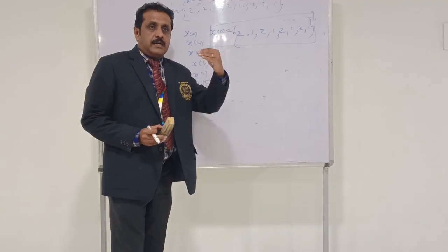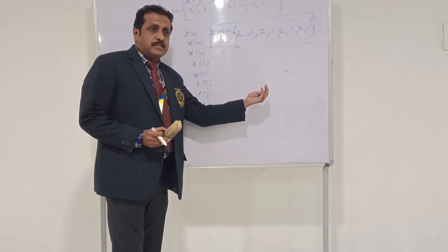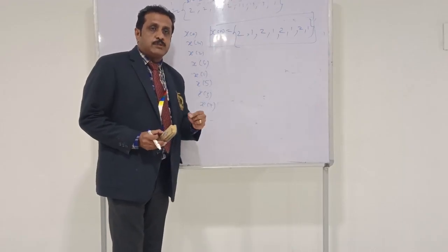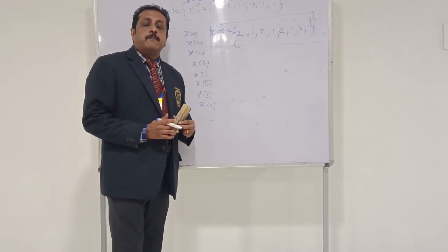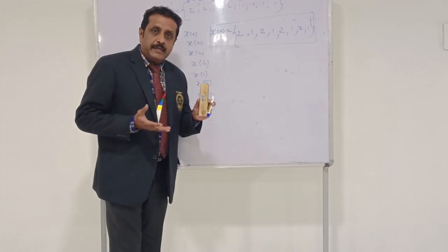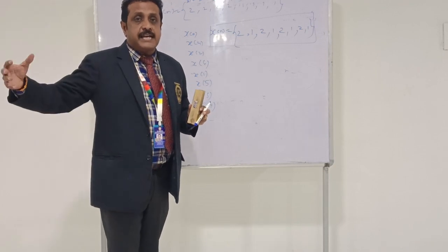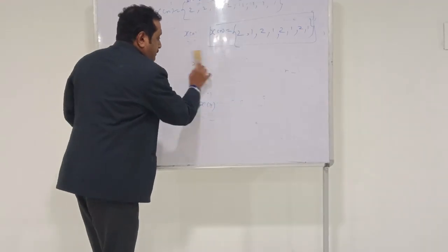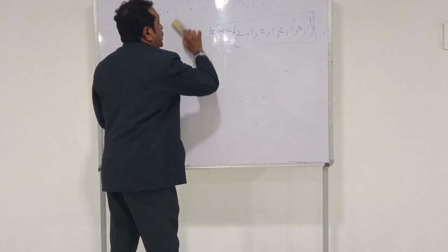Now we start applying the algorithm process, and we start computing the DFT, discrete Fourier transform. For the flow of the computation, the first stage will have four 2-point DFTs, the second stage will have two 4-point DFTs, and the final stage has only one 8-point DFT. So let me start from the first stage computation with the sequence 2 1 2 1 2 1 2 1.